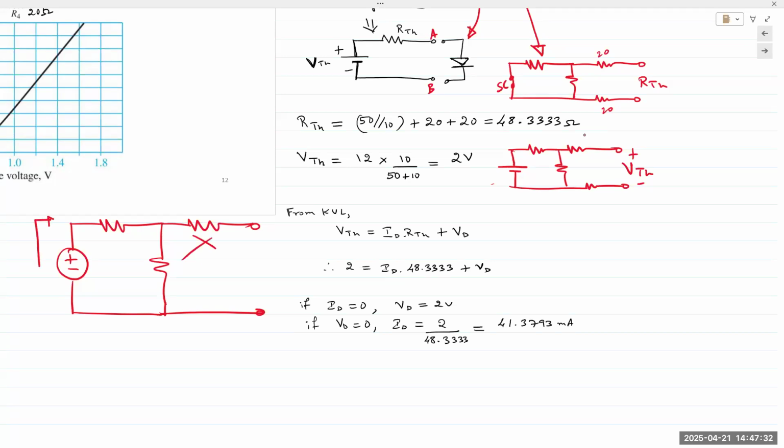All of the current is coming from the supply and goes down here, right? There's no current flowing through that open resistor. If there's no current flowing through the open resistor, the voltage drop is 0. Voltage is nothing but the difference in electric potential between any 2 points. If there is no difference between the 2 points, then V is equal to 0, which means both ends of the resistor are at the exact same electric potential.